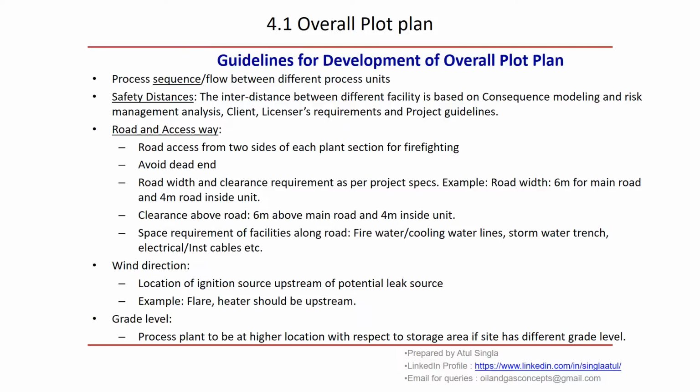In that space, we route fire water, cooling water, stormwater trench, and electrical and instrument cables. So, considering these things, we need to allocate proper space along the route.